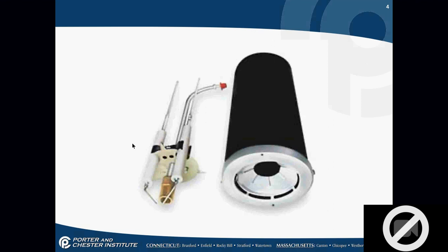So that's my whole key on these electrodes. They have to be lined up the certain distance above the center of the nozzle, distance apart, and distance in front of the nozzle.